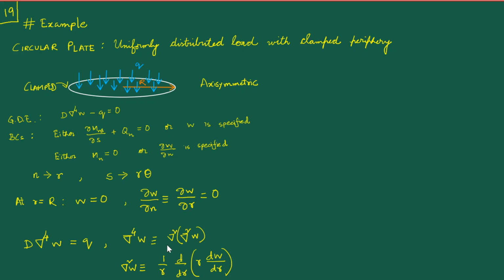So we'll have to do this del square of W, and this should be quite familiar to you if you go back to the notes of applied elasticity, where we dealt with the biharmonic not of the W but of the Airy stress function back then. So in terms of the mathematical form that it takes, it is absolutely the same. No matter what the specific form is, you understand that it is involving derivatives with respect to r.